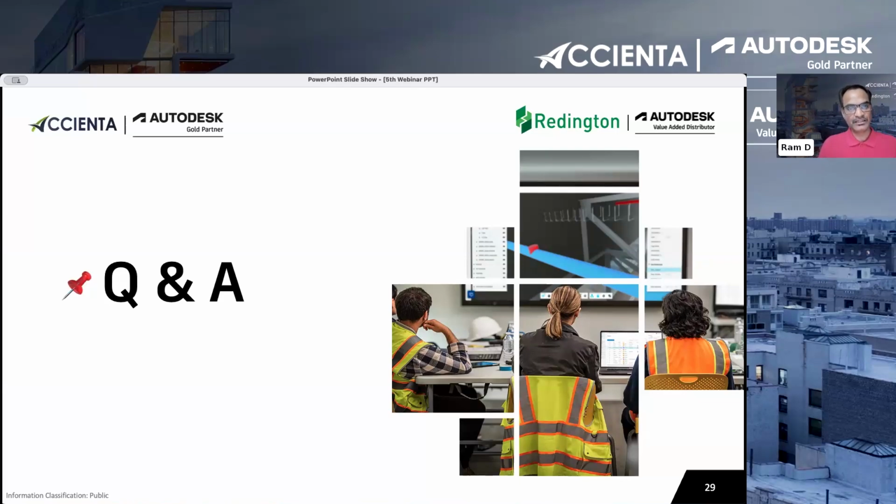But if you ask me about the hardware requirement for Civil 3D, yes, it is necessarily mandated, because the hardware requirement for the companies who work in horizontal projects is different than for vertical projects. Horizontal projects consume more hardware. So I always prefer to go with the minimum recommendation of 32 GB. I think most organizations are beyond that. And also a minimum of 2 GB graphic card, with a proper NVIDIA Quadro or NVIDIA RTX.